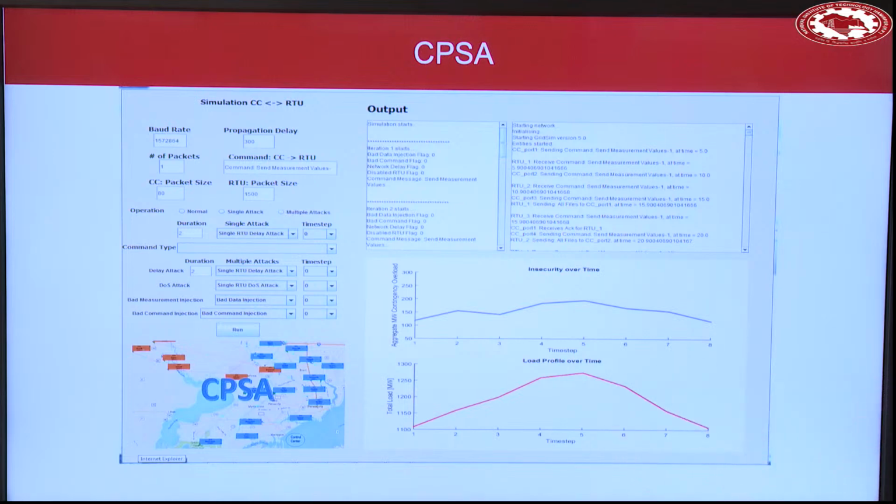Polling means you are requesting the RTU to send the data, right? So everything is done in a command way. The control center sends a poll command to all the RTUs at the substations, expecting them to send their data at this point in time. So what will the RTU do? Through sensors, they sense current measurements from the devices, send them back to the RTU, and the RTU sends them back to the control center.